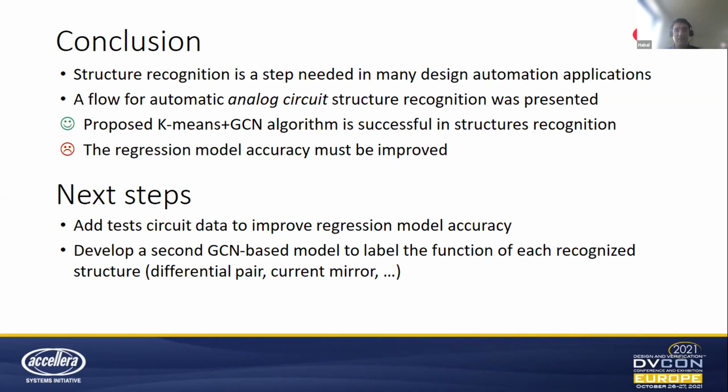So if the user added in the schematic some logic or some registers, then these also should be recognized by our algorithm. We also have some pre-processing to label blocks, for example, as digital or not interesting to our tool. We do this usually by the name of the cell or the library from which it is taken, right? So in this way, we can throw away some information during the pre-processing step.